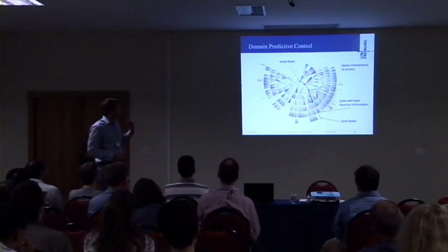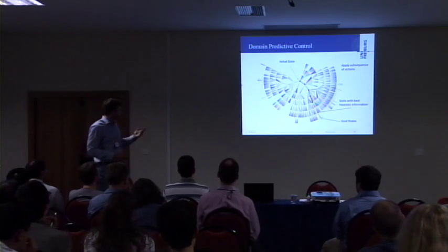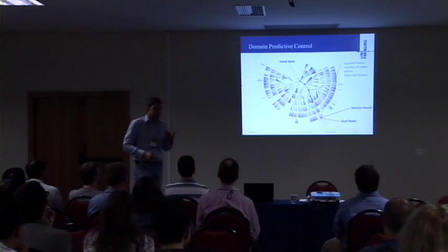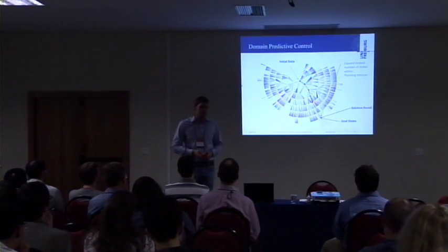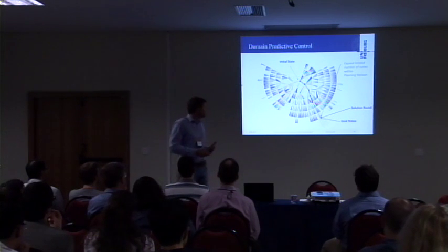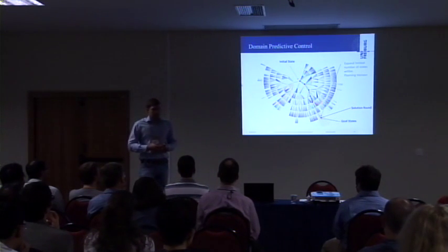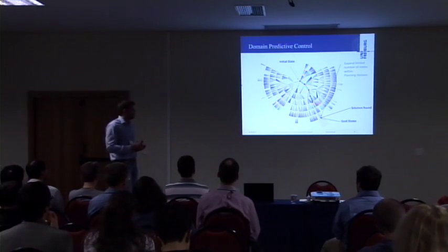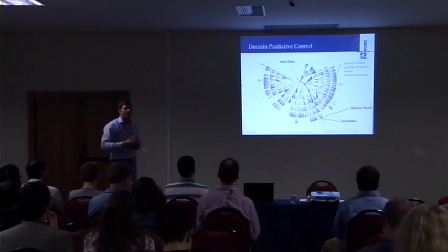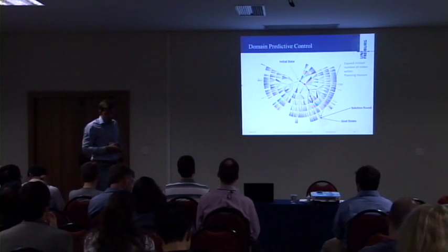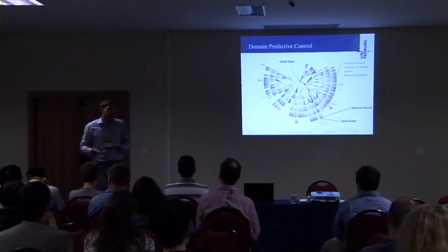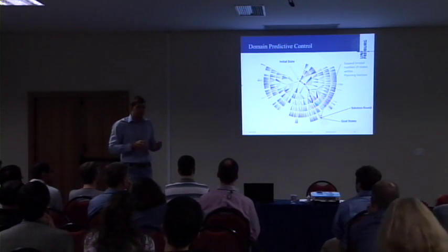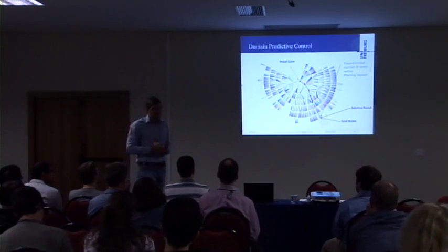Again, we apply a subsequence of actions towards the state with best heuristic information. Again, the horizon is receded until we have spotted some states which satisfy our goal conditions, and then we have found a solution. Of course, if we increase the number of states to be explored by the planning algorithm, and if we increase the prediction horizon, then we will reduce the possibility of ending up in a dead end. But this is finally simply defined by the computational resources we have available.